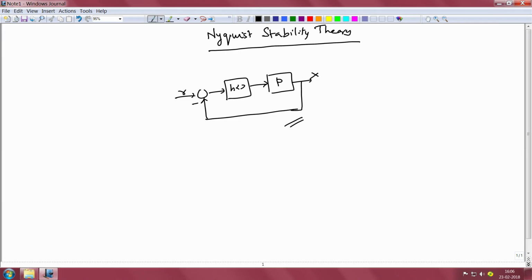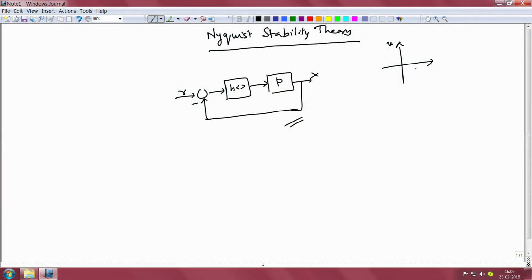The most common controller is the on off control, which we see in our refrigerators, in our air conditioners and many other such thermal systems. So what do we have there? We have the output u of the controller related to the input E in terms of a step change. So if E is greater than 0, u is plus 1, if E is less than 0, u is minus 1. One can view this kind of control action as the limiting case of a linear controller with saturation.